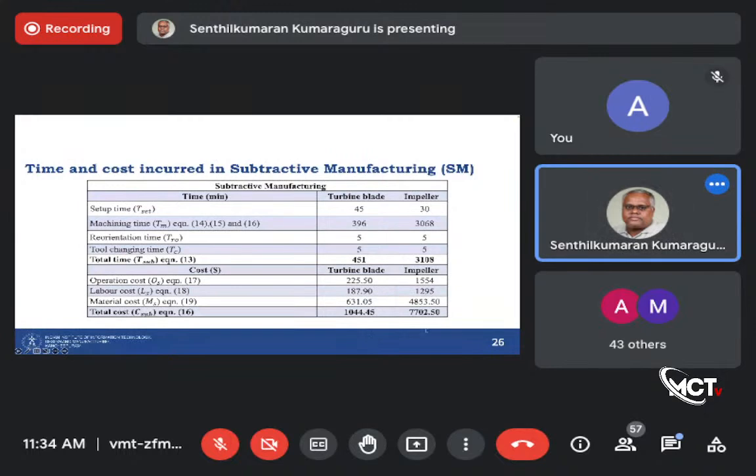So if you look at cost-wise, sorry, this is the total cost, this is the time. I'm sorry, 451 minutes is the time, and 3,100 minutes is the time. And $1,000 is the cost, and $7,000 is the cost for the impeller. So this is the cost of subtractively manufacturing a turbine blade, $1,000. And $7,000 is the cost for the impeller. One impeller costs this much to make in subtractive manufacturing, considering the bulk of it is material.